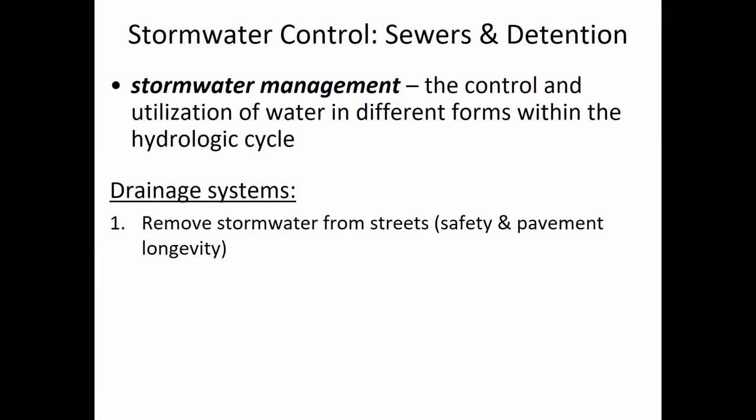So urban stormwater management is trying to control the hydrologic cycle, and really the effects of the hydrologic cycle, on areas that have been disturbed. When we urbanize an area, inevitably we're increasing the amount of impermeability by adding roof areas and concrete walkways and paved areas. What we're doing is limiting the amount of water that can infiltrate to the soil and increasing how much of it is going to be running over the surface, getting into ditches and getting into ponds.